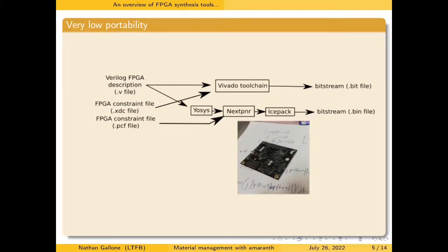For the latest iCE40 boards, which are cheaper, you'll need some open source software which separately executes the synthesis operation, the placement and routing operations with nextpnr, and the packer to finally adapt the LUTs and flip-flops to your iCE40 board. However, you don't need the same constraint file required by nextpnr, and you won't get the same bitstream format either.